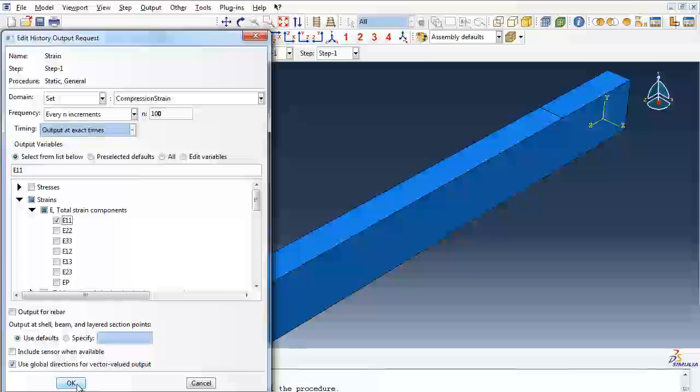If you had a compression analysis, say of a concrete cylinder being compressed, then you will need to go in all three directions, 1, 2, and 3, and so on and so forth. But in our case, the only data we have to compare for this particular analysis is the unidirectional strain gauge data we got from the lab, and that's what we're gonna use.